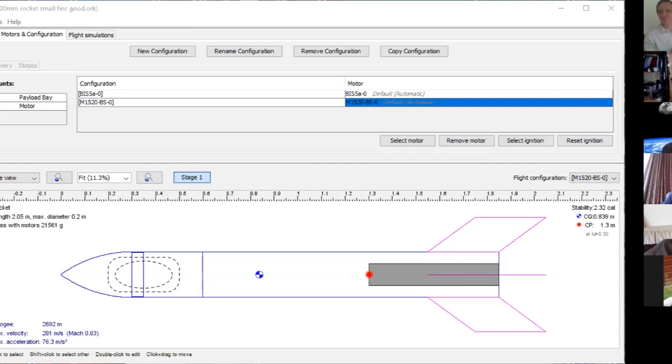For a multi-stage rocket, it came as quite a surprise to me that there weren't any proper algorithms for designing one. I mean, there are certain rules of thumb, but there isn't an equation you can write down to say how much you need from each stage and when your staging should be. So I actually did a big Monte Carlo simulation to work out the staging strategy I wanted to use.